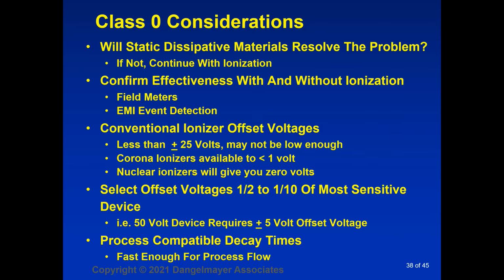And of course, we must have process compatible decay times. There's no point in having a decay time of 60 seconds if the product is only exposed to the ionizer for 3 seconds. So the ionizer decay time must be fast enough for the existing process flow.